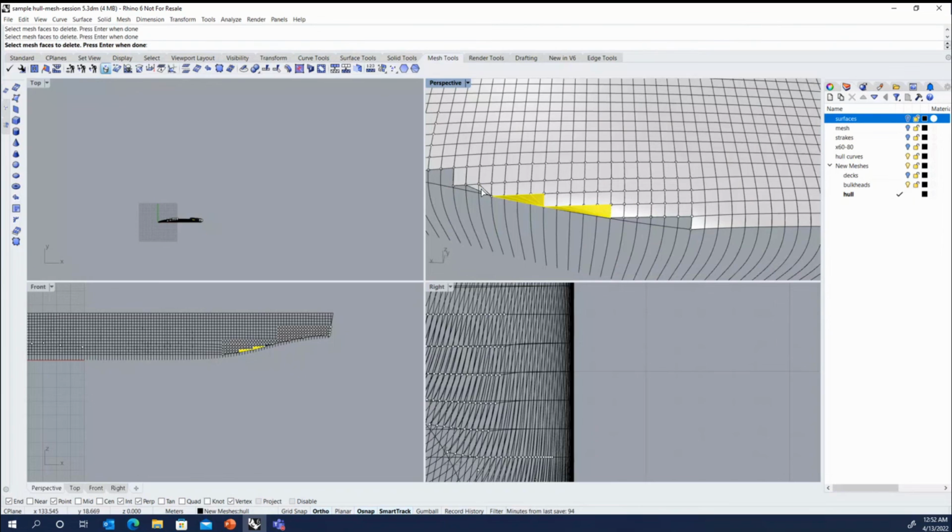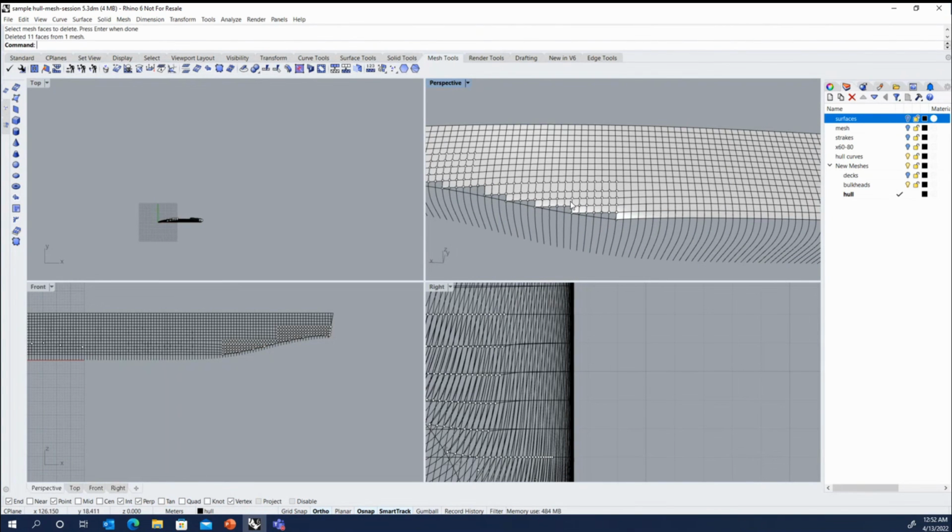I have used that when I was creating stiffener traces on a hull from an expansion drawing. Now, if you have a 3D model and you already have your stiffener traces in 3D space, it makes it much easier to generate these traces in your 3D model.